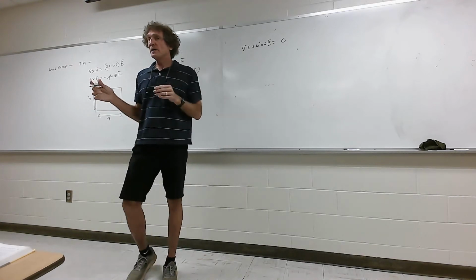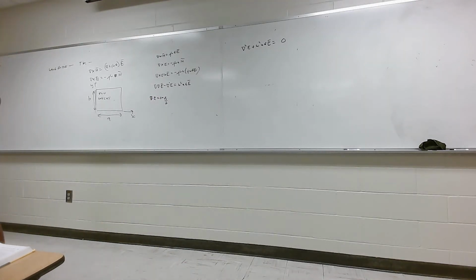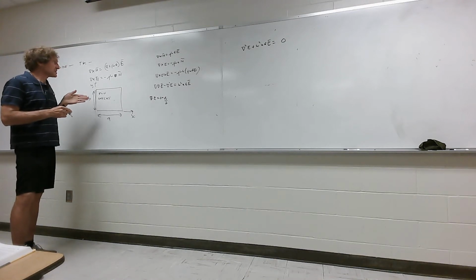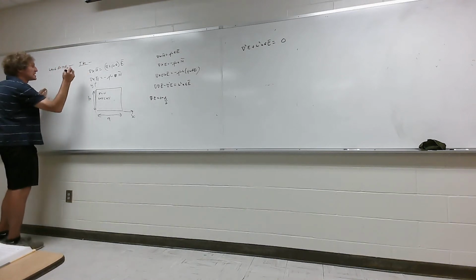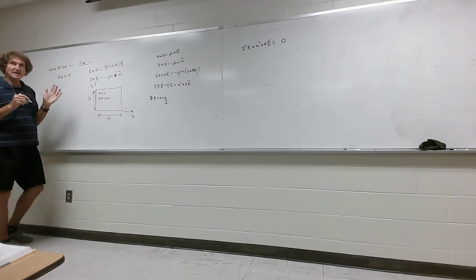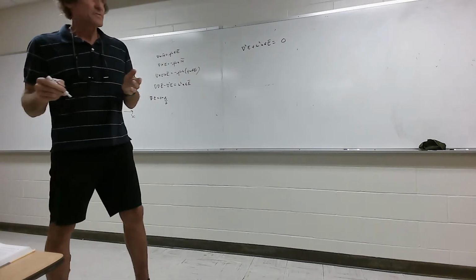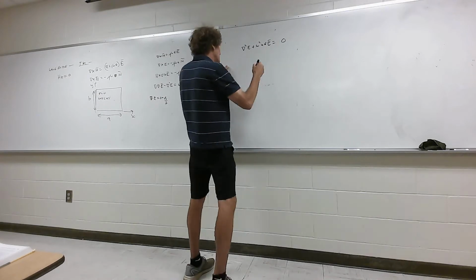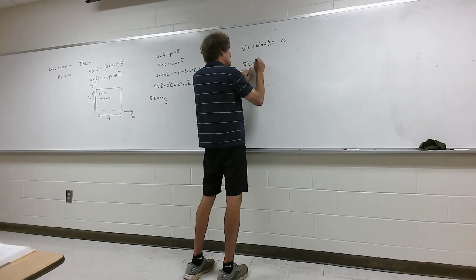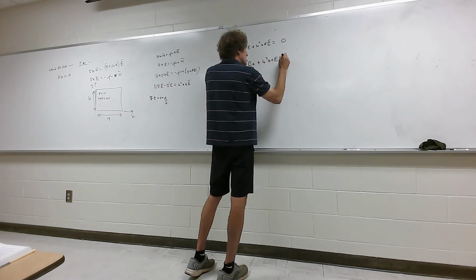So with a waveguide, you take a look at that differential equation for one particular E field polarization, and that's the E field in the z direction. That's how come it's TM. Transverse magnetic means HZ equals 0. There is no magnetic field in the z direction, there's only an electric field. This equation becomes del squared of EZ plus omega squared mu epsilon EZ equals 0.